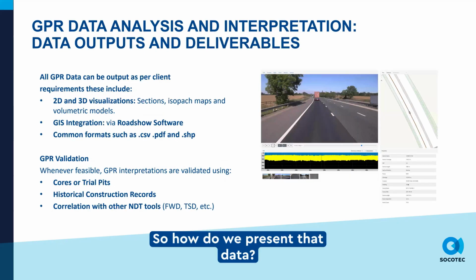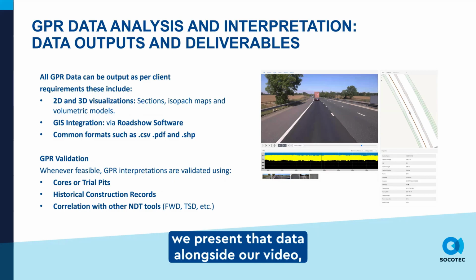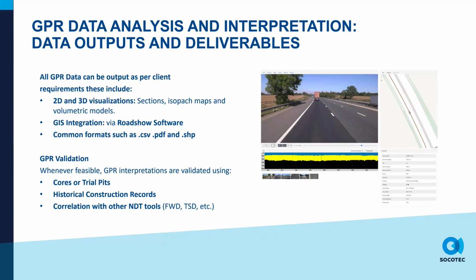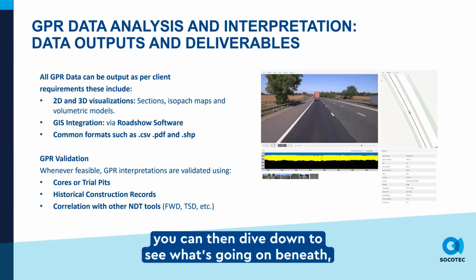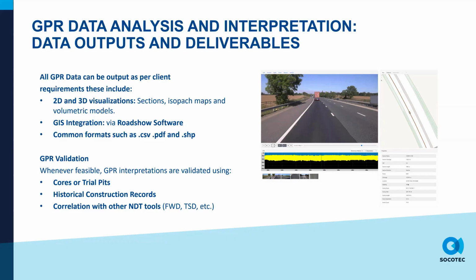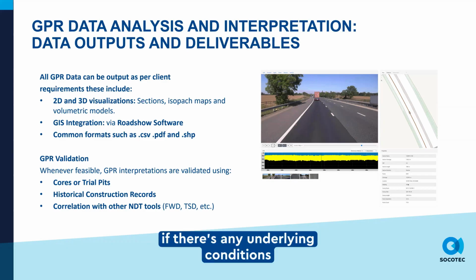So how do we present that data? I touched on it a little bit earlier. We present that data alongside our video, which sits within our Roadshow software, which is why we like to collect in the daytime. This gives you a good indication of what is going on above the surface and what's going on below the surface. So for example, for a reflective crack located on top of the surface, you can then dive down to see what's going on beneath, whether any excess moisture has seeped into the pavement, or if there are any underlying conditions that have happened in there.